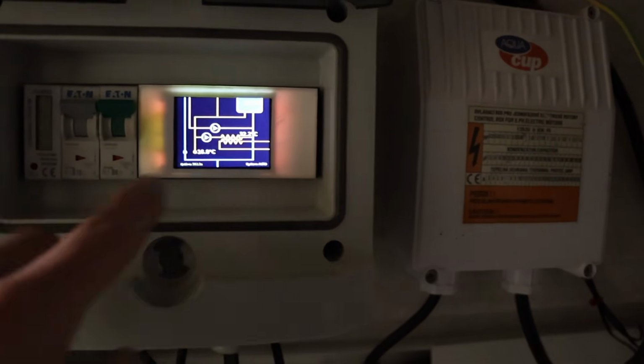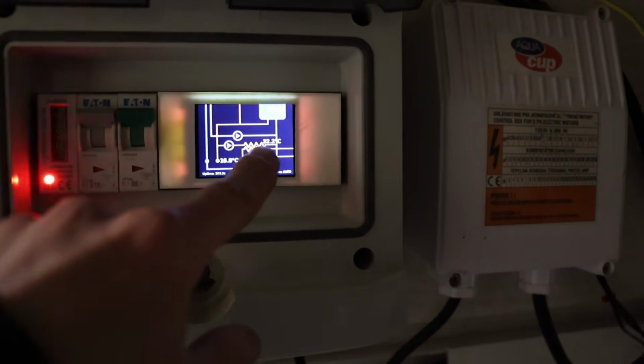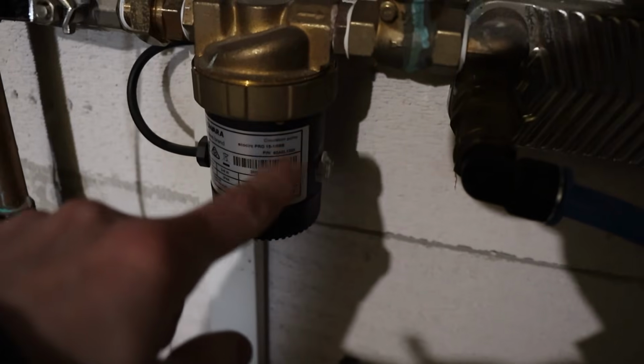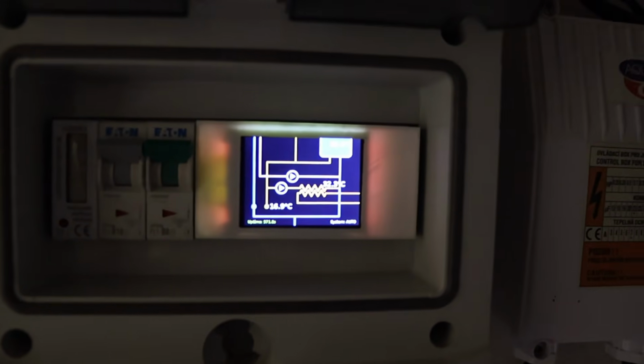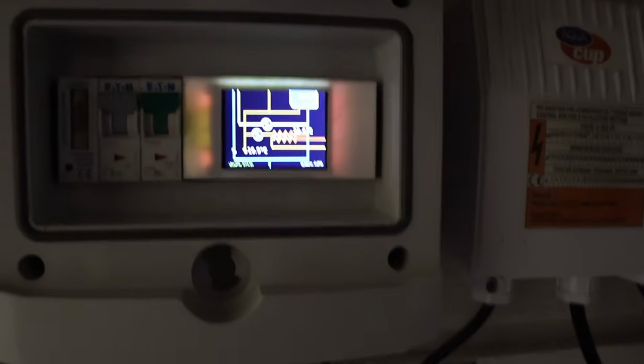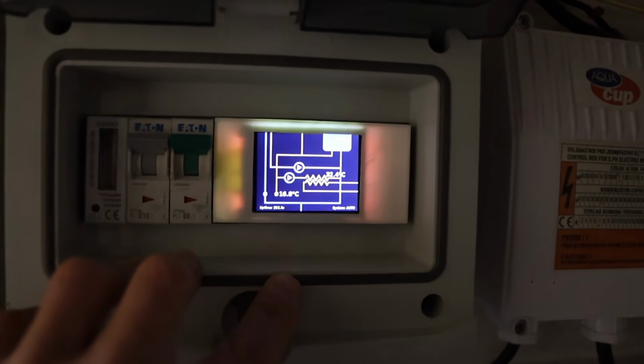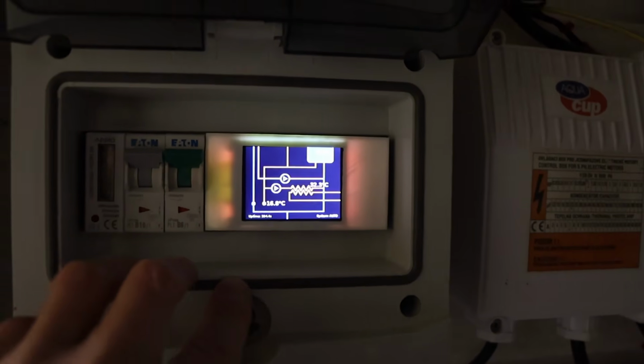It's just when the temperature in the exchanger is at the threshold and I run the water, it blinks the pump on and off. But I have added some hysteresis to the exchanger pump too, so this wouldn't happen. But also I could add some low pass filter in the software, so that should do the thing too.